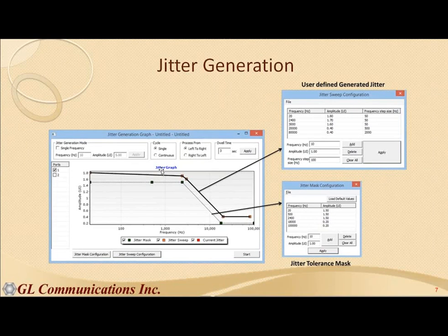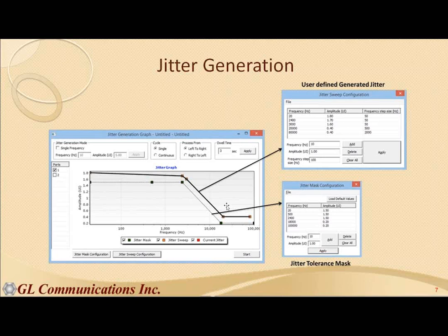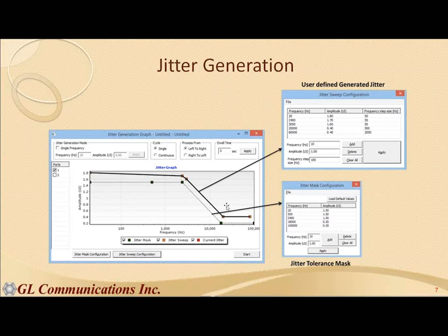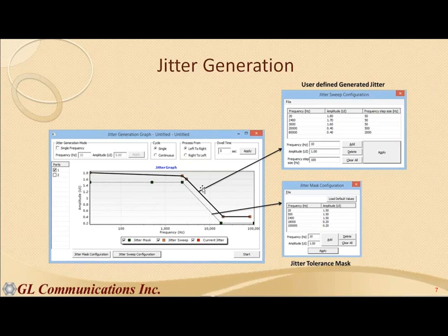And now, you have to understand what jitter is. It's frequency dependent, and it's also amplitude dependent. A particular T1 pulse or E1 pulse has an ideal clock and timing associated with it. But if it deviates from that in any way, then we call that jitter.